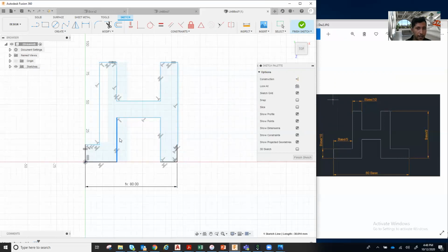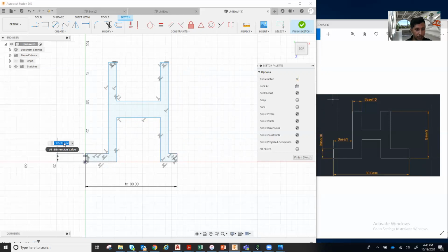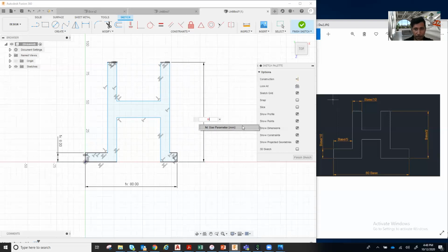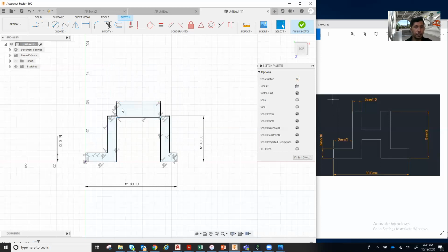Okay, I just ensure this shape. So it should look like this hedge section. So the next step, the dimension, this should be thickness, TH, right? And automatically you can see all this thickness has been updated because I have already given all this equal constraint. And the height. So this height is supposed to be HT. Already I have given the parameter. You can see the HT user parameter is already there. I just press enter. And this shape, I just ensure it comes below here.